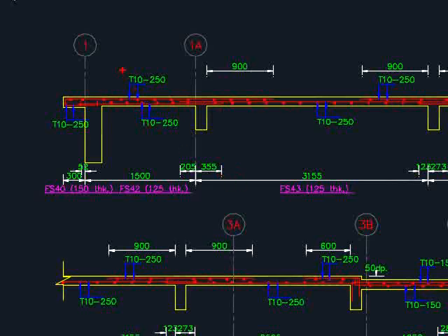And then you're going to lay the reinforcement bar, as you will consider the slab to be continuous. There will be reinforcement bar at the bottom of the midspan as well as the top reinforcement bar at the support. When you provide the reinforcement bar at the top of the slab, you will need to clearly indicate where this reinforcement bar ends.